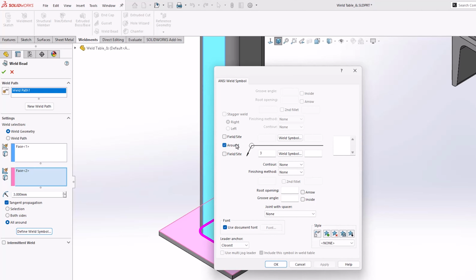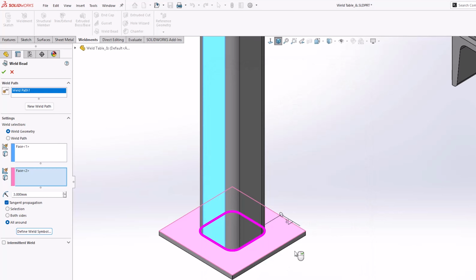As you can see, the around option has propagated over from the property manager, also including the proper symbol as well. Here we can input the notes. We can also select a different type of weld symbol here. Once we're done with the definition, we can click OK, and the weld symbol will be included in the 3D model.